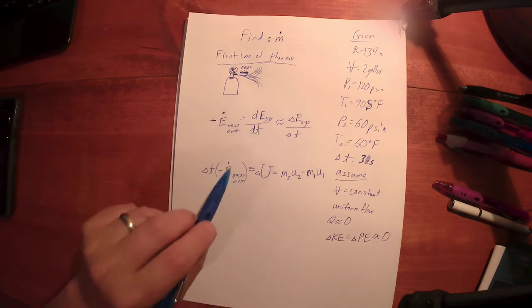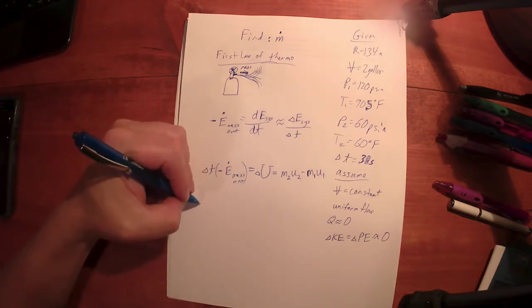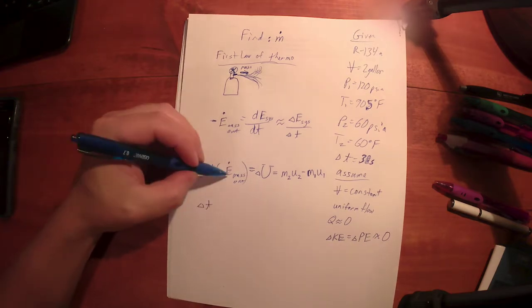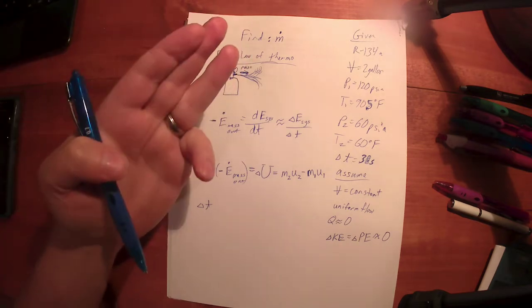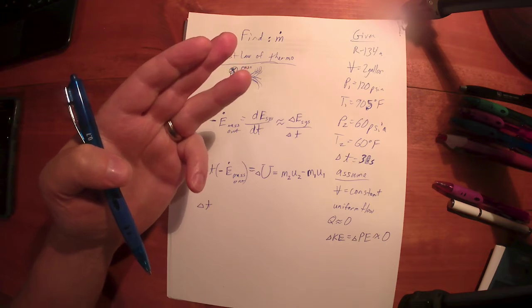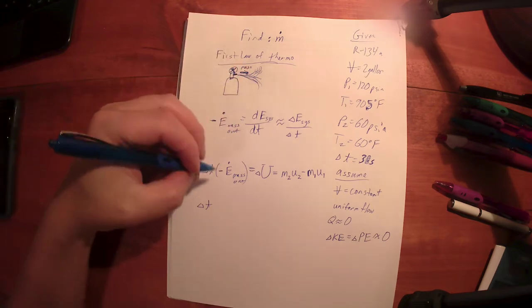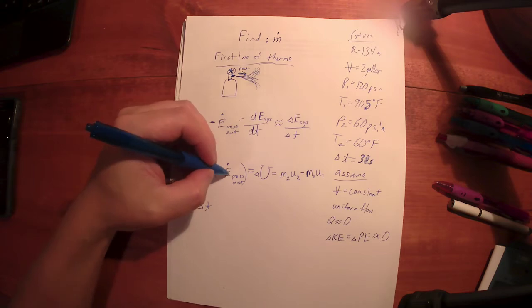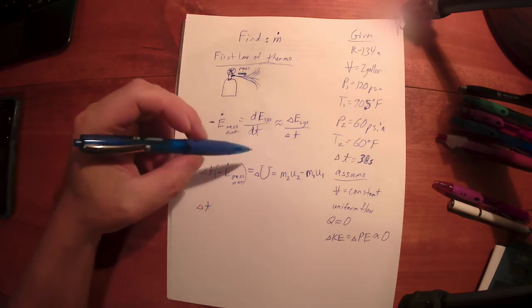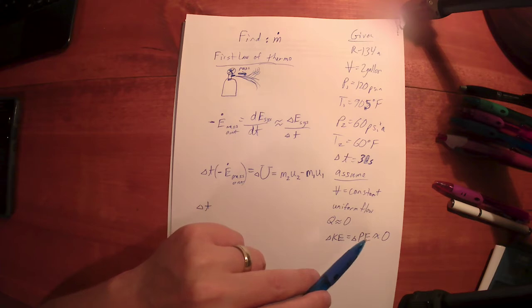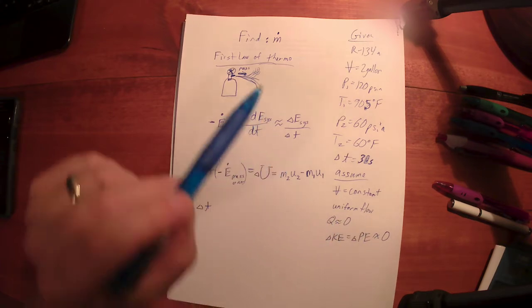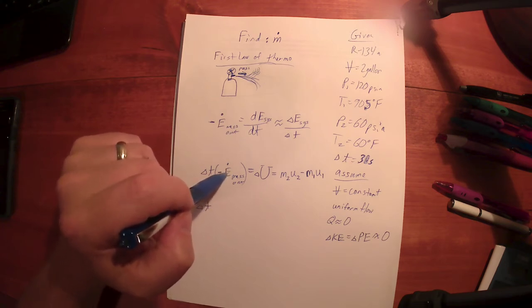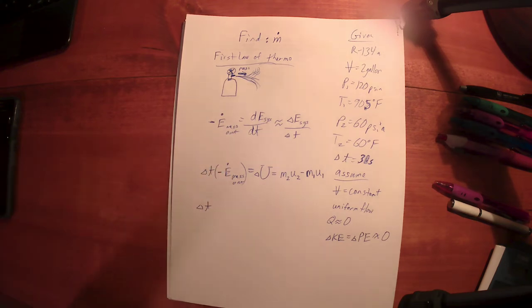Now, if we look at the energy of the mass out, as we've talked about throughout Chapter 5, this mass has its own enthalpy, its own kinetic energy, and possibly its own potential energy. So again, this has h, V, and z. Well, we don't have enough information to worry about the z value, or the potential energy. Now, we talked about what you do as far as the kinetic energy of the mass out or the mass in, and we say, well, is it a nozzle or diffuser? If it is, you have to consider the kinetic energy.